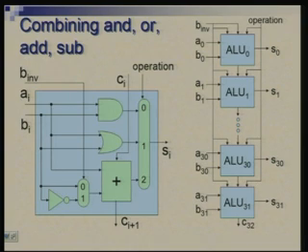Going further, as far as add and subtract are concerned, there are 2 different types of add instructions, add and add unsigned. So, there is ADD and ADDU. Now the question would be why we have 2 separate instructions, add and add u, when we have said that addition can be done with the sign ignored when you are using 2's complement representation. Then what is the purpose of having 2 different instructions? Okay. The reason is that there is something which we have ignored here, which is the detection of overflow.